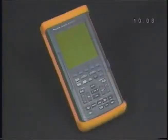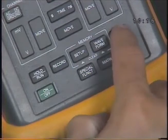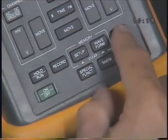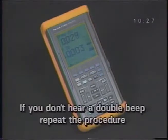We'll start by performing a master reset. Make sure Scopemeter is off and remove any test leads. Press and hold LCD. Press and release on-off. Then release the LCD button. You should hear a double beep. That tells you the master reset was successful. If you don't hear a double beep, repeat the procedure.